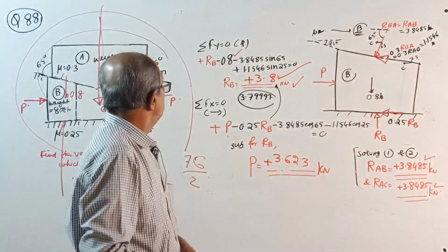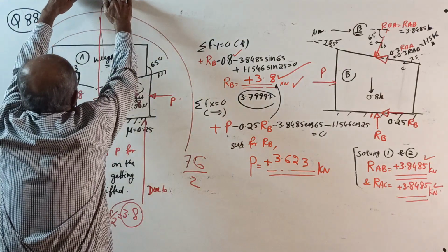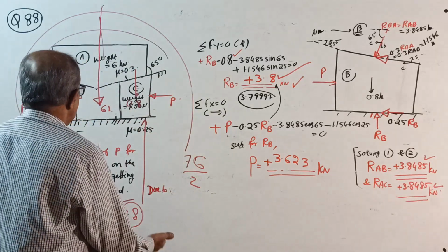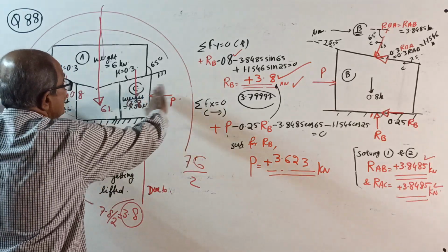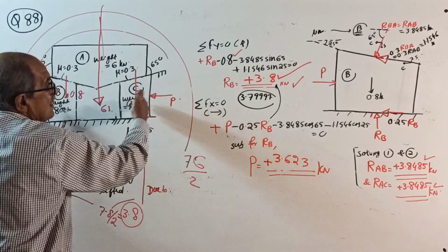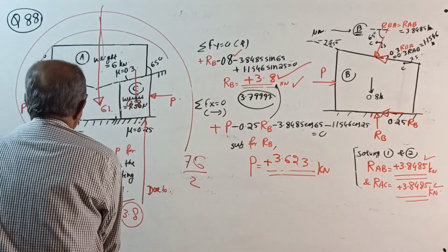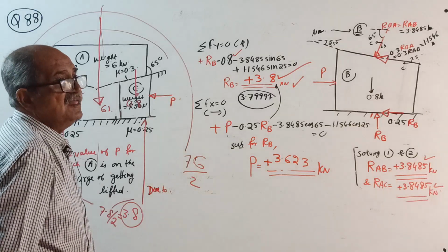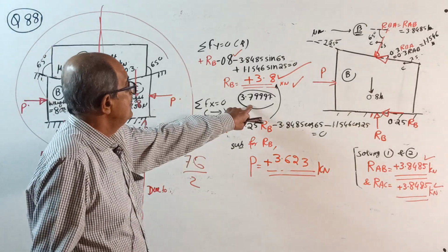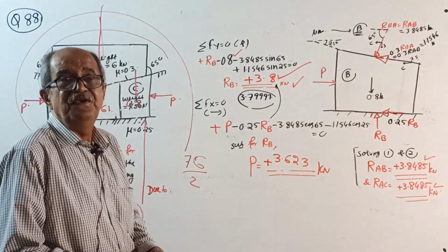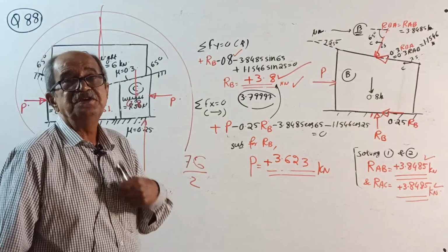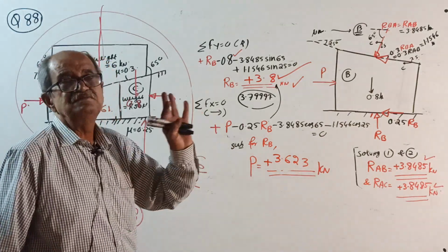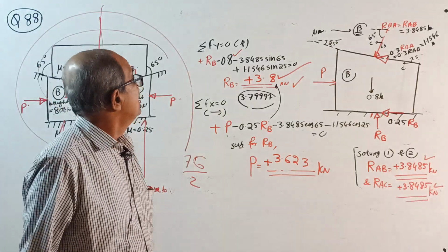I know the answer. By looking at the arrangement only I know it. See, if you apply a load this way to 6, 0.8 plus 0.8, total 7.6, two horizontal supports. See, no reaction will come this way. See, there is no contact here. So therefore, for equilibrium, if total load is 7.6, each will get downward load of 3.8 kilonewton. Correct, see, 3.8 kilonewton. See, this is where your structural knowledge counts. Anyway, by chance, if I have not observed, if I rub the board and went, it is not technical mistake. It is a print mistake.